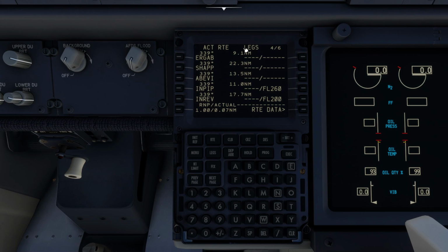We're going to skip through our route to make sure there's no discontinuities, and there's one. And I knew there would be one. What this is, between the end of the standard instrument departure and the beginning of the approach into Edinburgh, the standard terminal arrival route, and the approach into Edinburgh, there's a gap in the flight plan, which is essentially our own navigation. So we could just delete this gap. In other words, the aeroplane will go straight from Tartan straight to CI24. To do that, we just select CI24 and then pull it up over the top by clicking on the blank area, and it will pull everything up.